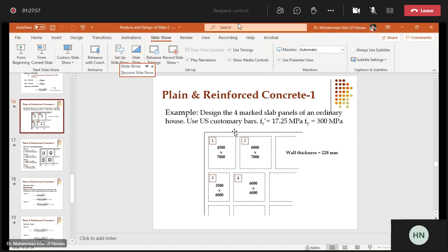So next our topic is to design the flat plate system, a slab which is only resting on columns, because in multi-story buildings you know there are a lot of ducts and pipes running under the slab. If you go for a lot of very deep beams, then one option is to pass the pipes through the beam, which is not a good option, because you can't make a lot of sleeves in the beam.